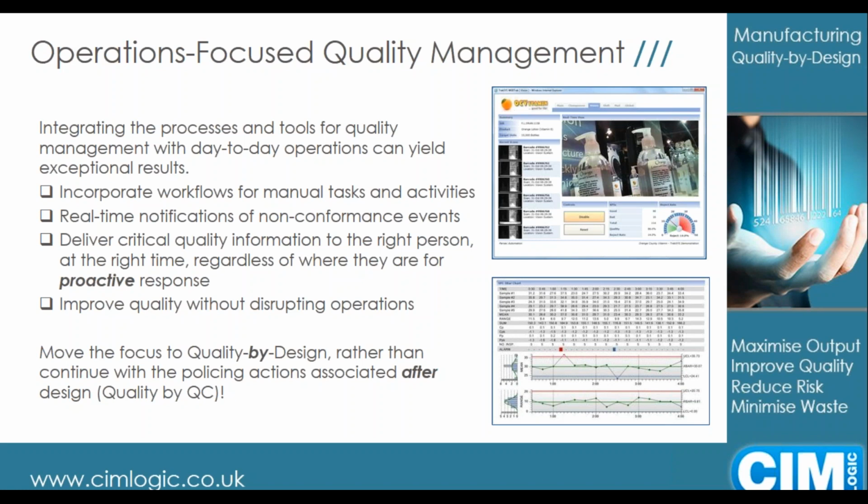We're going to be able to identify trends. We're going to be able to make predictions. If you look at, for example, the SPC control chart at the bottom right of the slide there, we can be starting to incorporate things like the rule of sevens. So if we're looking at maybe 6 or 7 previous sample points that all seem to be trending upwards, we're still creating saleable product to this point. Nothing's exceeded any threshold, but we've had 7 points that are all trending upwards.